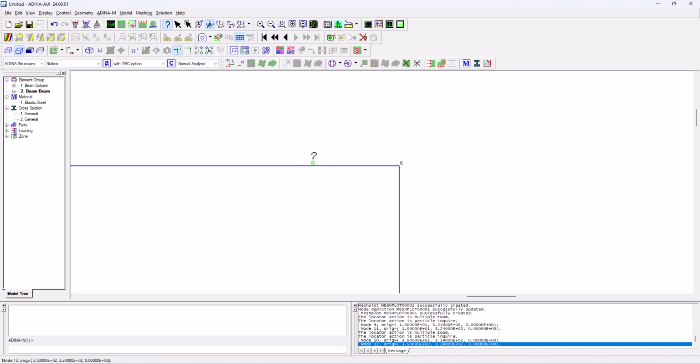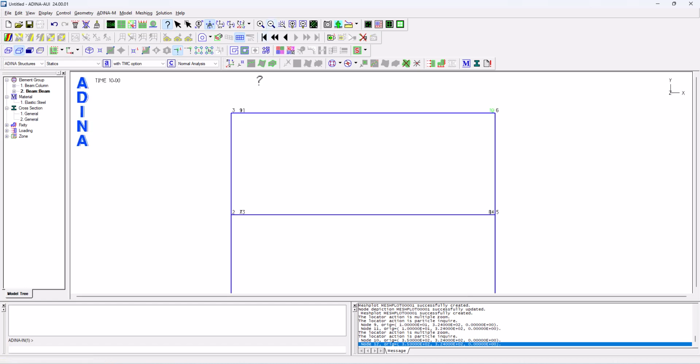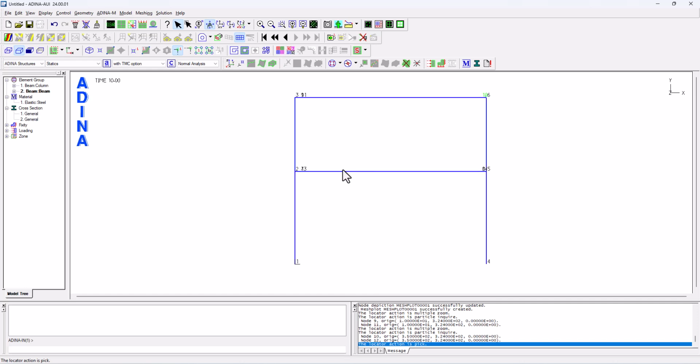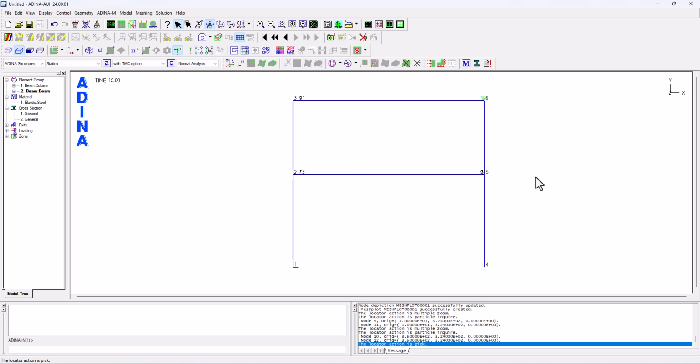And this will allow me to introduce some 0 length link elements that will be my moment hinges, my plastic hinges. And for that, we need to have 2 coincident nodes. So this concludes this first part of this model, where we have everything except the link elements. We're going to show how to add the link elements in the next video, in the next part number 2.